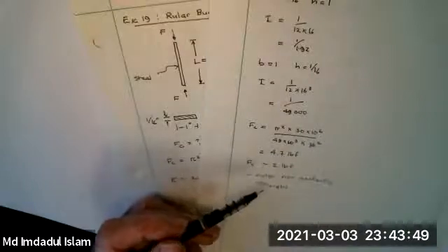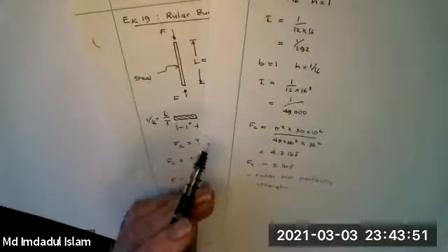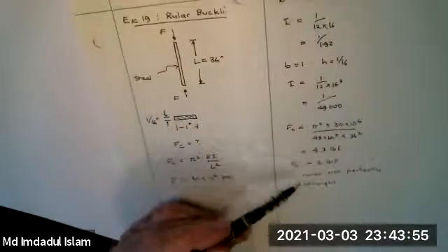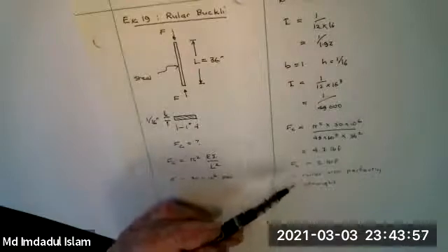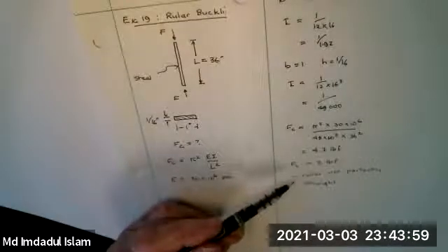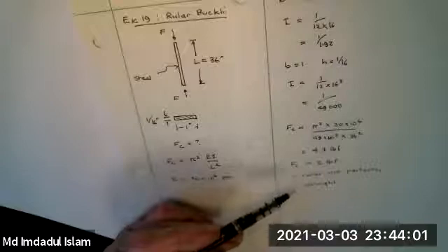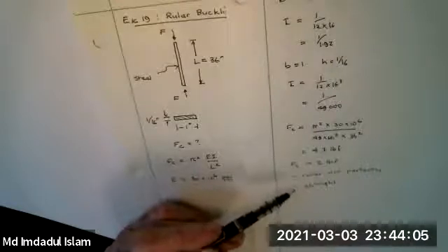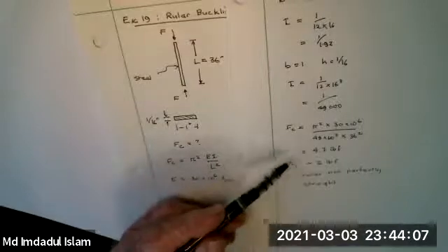By and large, we're not going to load things like rulers in practice, okay? And so you get very light buckling loads. When you get very light buckling loads, imperfections can drop them by a factor of 2. You get more realistic mechanical engineering components, they're considerably more squat, okay? And so you don't get as big a factor as this.